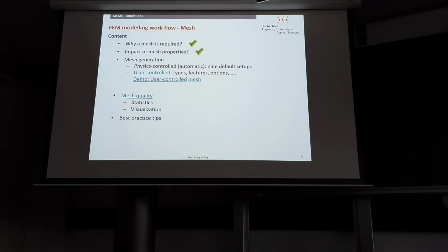In general, it follows the philosophy COMSOL has in many parts. First of all, COMSOL tries to provide a default mesh, which is definitely not optimized, but something to start with, to get some first results. So this is also a topic in progress. Physics-controlled means that the COMSOL program tries to analyze your model, what physics you are using in particular, and from that information tries to provide an automatic mesh which should already work to some extent.